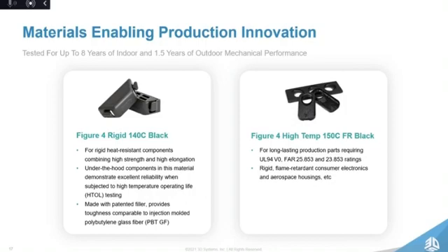Temperature extremes and fluctuation, impact resistance, and UV and moisture resistance. In automotive applications, for example, temperatures range from -40 to +120 degrees C. And these materials will accommodate that quite easily with little loss in mechanical performance.